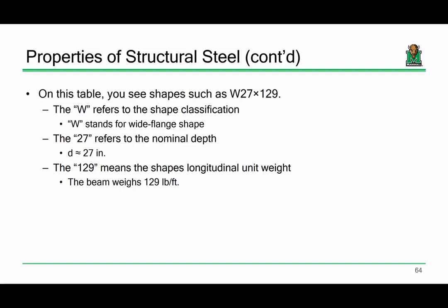There are some really fancy scanning techniques where they'll develop a 3D rendering of the girder. I was actually at PennDOT not too long ago, and they were showing off this scanning system that they had. It was really neat. They would have an I-beam, and it was almost like GIS-type equipment, collecting point cloud data along the girder. You would take that point cloud data and overlay it on top of an ideal I shape. In that instance, what they were trying to do was measure girder imperfections during fabrication.